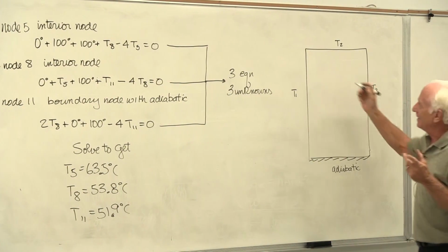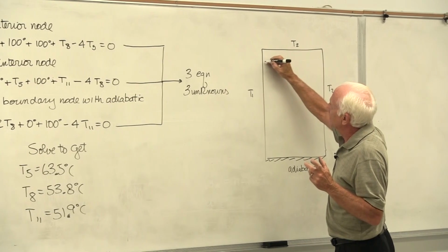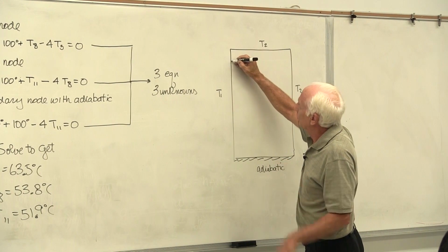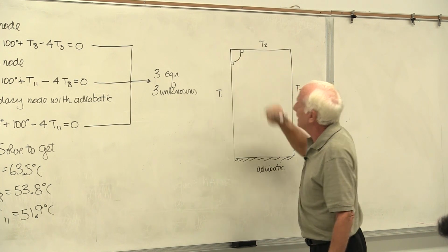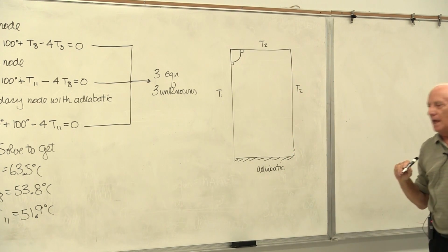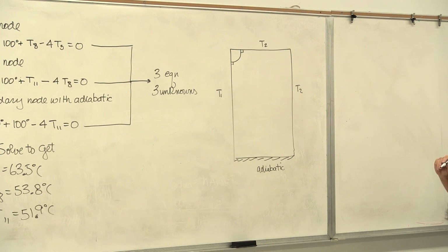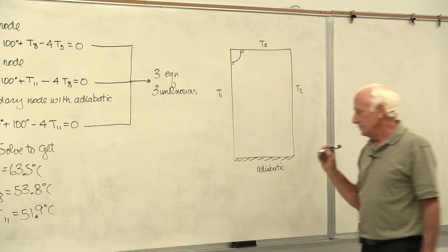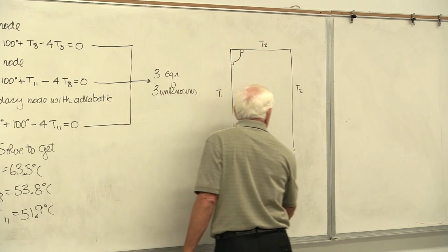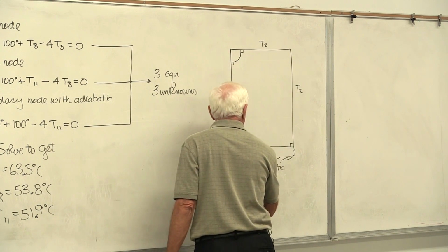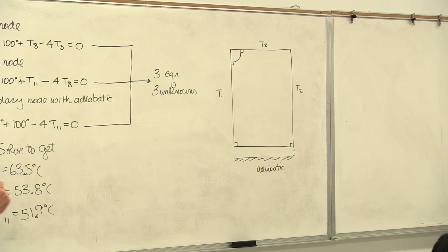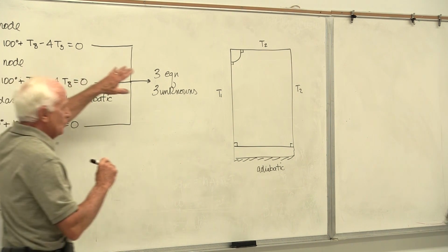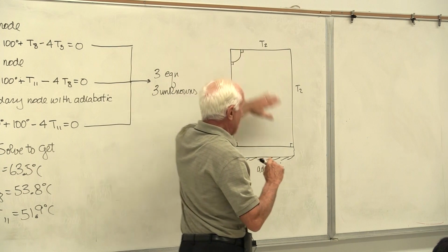So, draw the heat flow lines. Obviously, heat goes from hot temperature to cold temperature. Upper left-hand corner, it almost makes a quarter circle. Right angle, right angle. At the bottom, the heat that leaves T1, high temperature, goes towards T2, but it can't get out the bottom. So near the bottom, it almost goes straight across. Now I've drawn heat flow lines, or what they call adiabats, at the 2 extremes, upper left-hand corner and near the bottom.